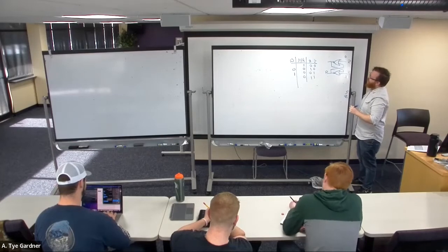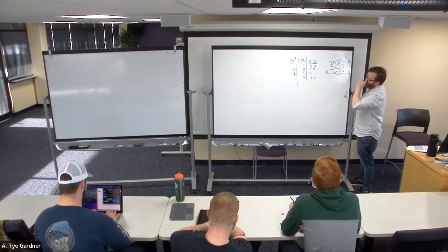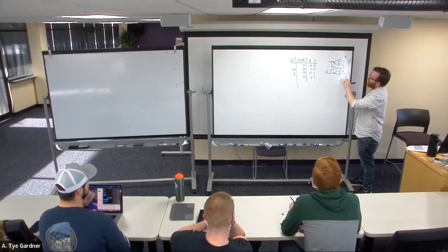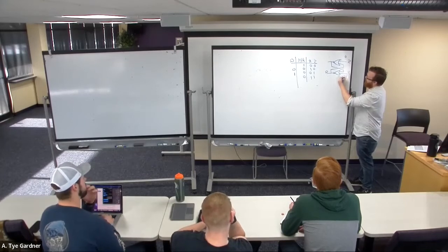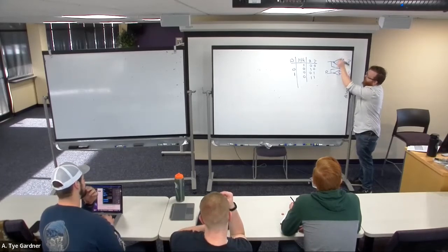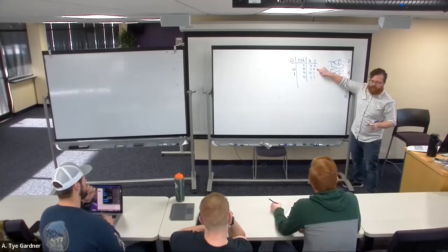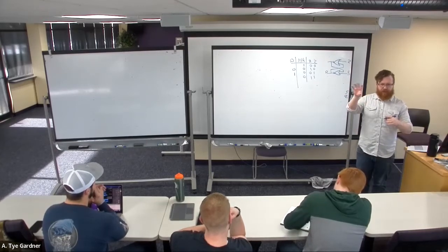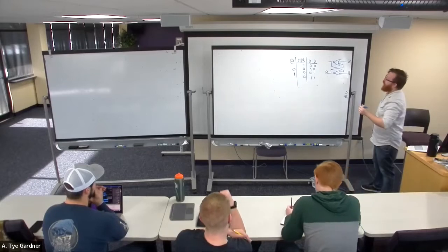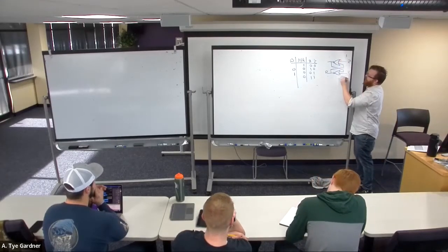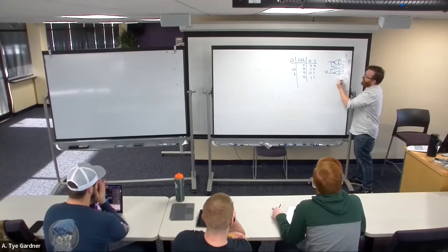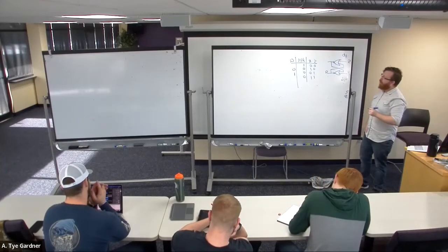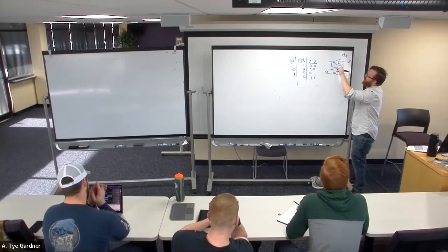And now, what happens if I change this 1 to 0? Actually, we're going to do this the other way, because those two are base conditions, right? Either I am just having S or just having R. But things are going to behave a little bit differently depending on the combination of them being both true or both false. And now let's look at that situation. The easiest way to do that turns out to be starting from S is 1, R is 0, staying with R is 0, but transitioning to S is 0. Okay. So when I do that, S is changed from 1 to 0.